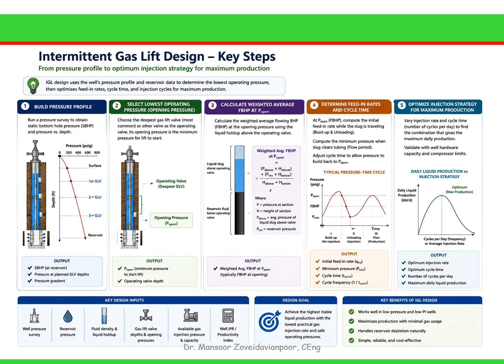Finally, we optimize the injection strategy. This is where engineering judgment becomes important. We evaluate different cycle frequencies and injection volumes to identify the operating condition that delivers the highest daily liquid production while remaining within compressor and gas supply limitations.